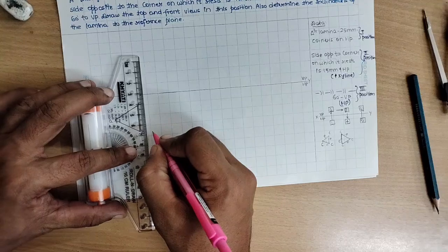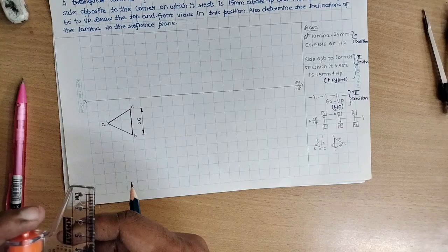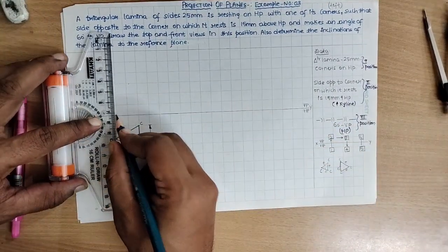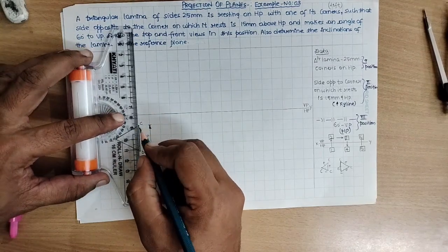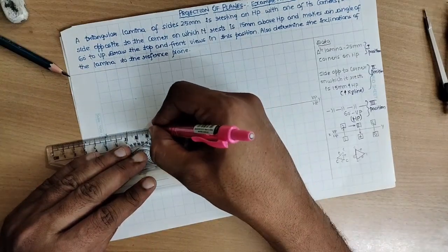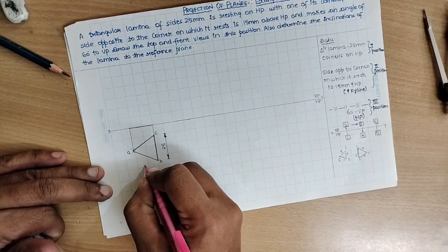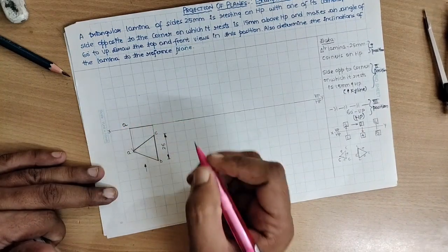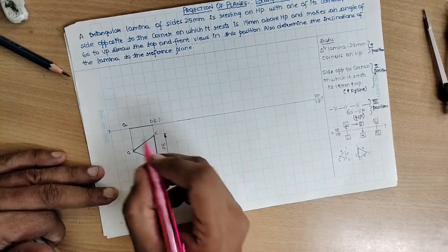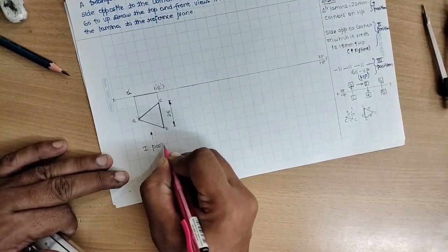I will show the dimension immediately. This is the position number 1, as we have already mentioned in the data. Make use of projection lines: projection from the point A till it touches the XY line, projection from the points B and C till they touch the XY line. Now connect the two end points. Since this is also a part of the object, this has to be increased in thickness. Observer is looking from this end. For the observer, A is visible, show as it is, B is visible, C is invisible, invisible in the brackets. Since it is the front view representation, show it with dashes. This is called the first position.